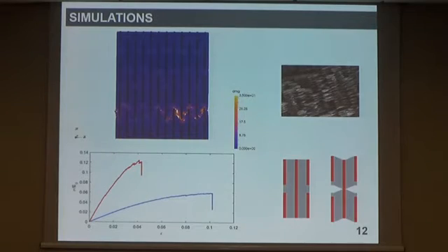So you will have optimization in the strength and in the stiffness with a relatively low loss of toughness. This is because when the damage accumulates in these tips, it will not propagate because it's shielded by the surrounding reinforcement. So this is a very interesting structure.